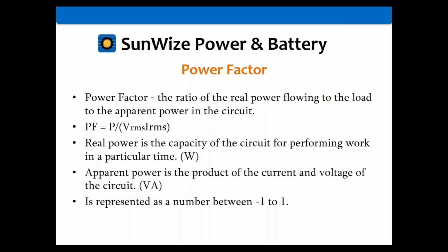Most loads are usually pretty efficient. You're going to find that in the 0.9, 0.95 range, maybe even something as low as a 0.8 or 0.85. That's generally not too bad. It's okay. It's actually rare, unless you've got a pure resistive load of some form, say a resistive heater, you're not going to get a 1. Generally, there's always some type of little bit of power factor there. But generally, if you've got a good, clean, efficient load, it's going to have a power factor that's still going to be pretty close to that 1 value.